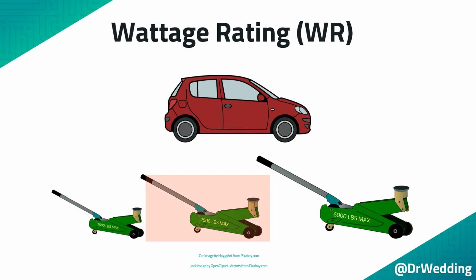Assume you have a safety factor of 1.5. You would multiply your car's weight by 1.5, and you would say, I need a jack that can handle 2,213 pounds. Using this safety factor, the 2,500-pound jack would be your choice. In this series, I will use a safety factor of 2 when choosing my resistor values.